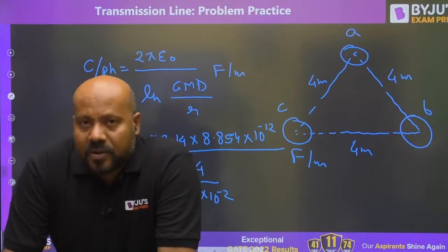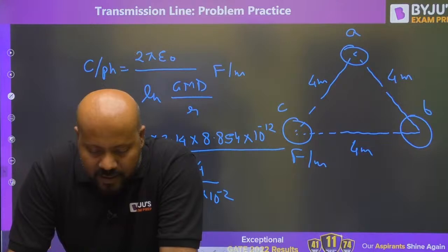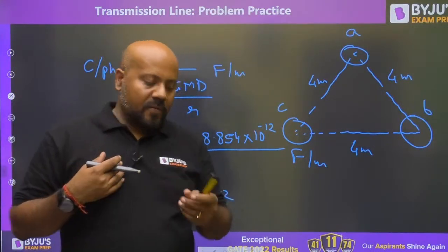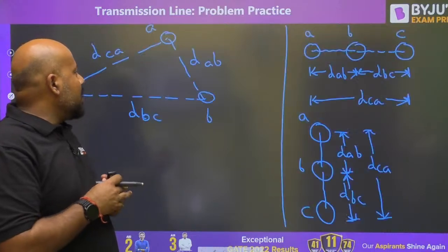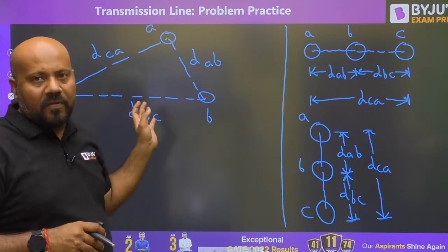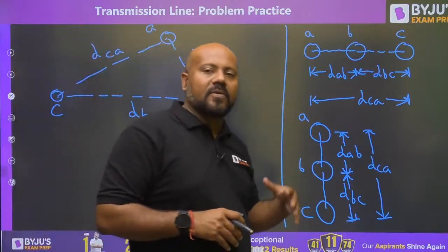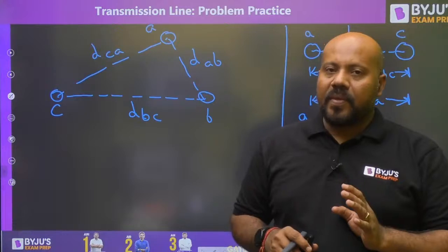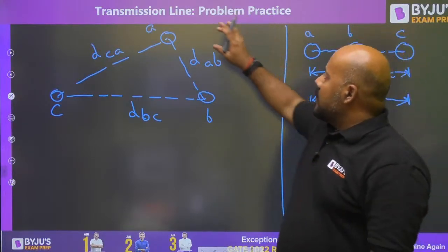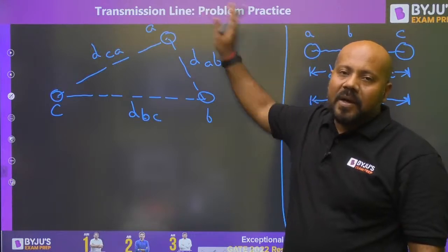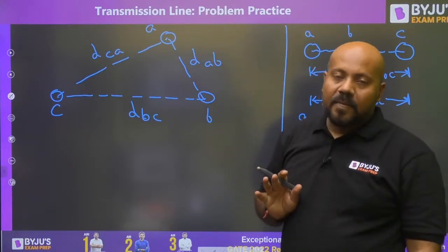No, Shivam, no limitation. Are you getting that? You must have this much common sense. If you have one conductor in A phase, B phase or C phase and different types of constructions or spacing are possible, you can apply this formula. But suppose this is not a simple conductor, but a bundled conductor, then you cannot apply this formula.